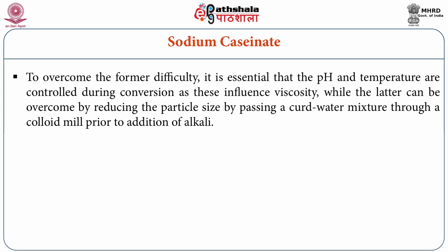it is essential that the pH and temperature are controlled during conversion, as these two factors will influence the viscosity of sodium caseinate solution. While the problem associated with the impervious jelly-like viscous coating can be overcome by reducing the particle size, by passing a curd-water mixture through a colloidal mill prior to addition of alkali.